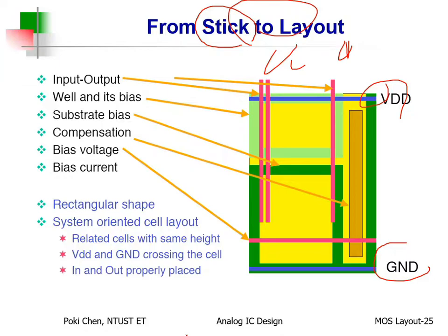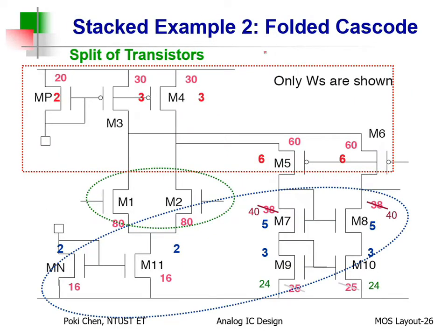Okay? But you don't need to do it by yourself because you have layout engineers in the analog domain or you have EDA tools in the digital domain. You don't need to make it by yourself. You simply have such kind of stick diagram to show them, I mean layout engineers or EDA tools, what you want. That's it. Okay? And hopefully with your stick diagram, the final layout will generate better result after fabrication.